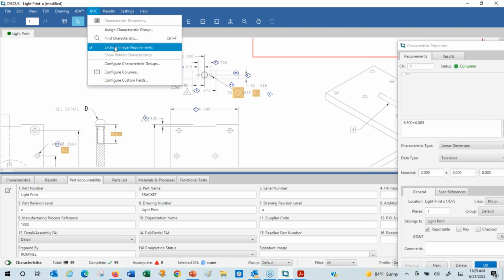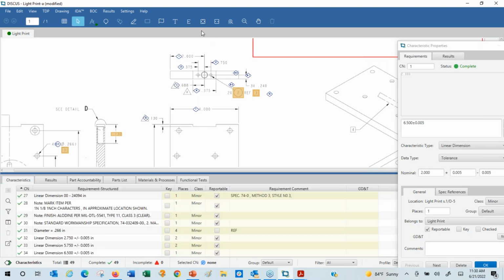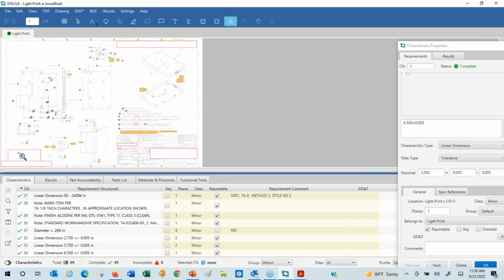Yep. When you want to manually balloon for the notes, hold the shift and drag it over the notes. That's for notes primarily. That's how they did it. And if you'd like to see that again, let me know. But when you want to manually balloon anything but notes, you just go through it and balloon it like you normally do.